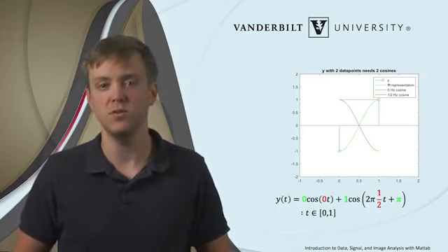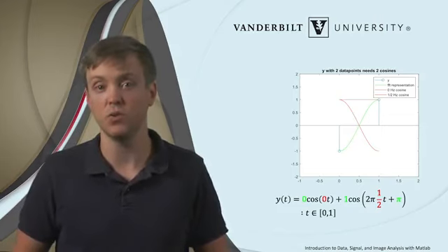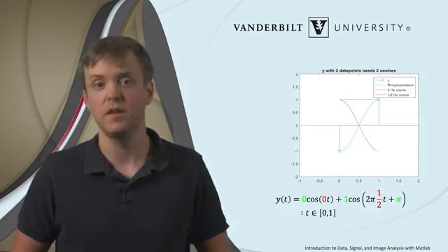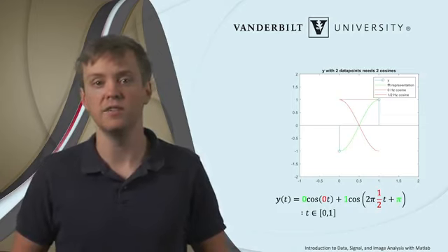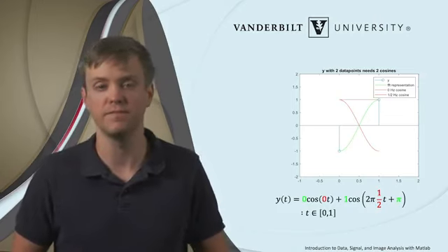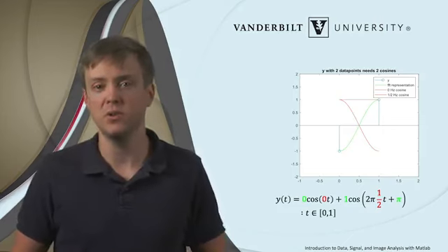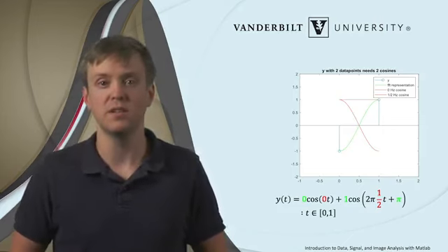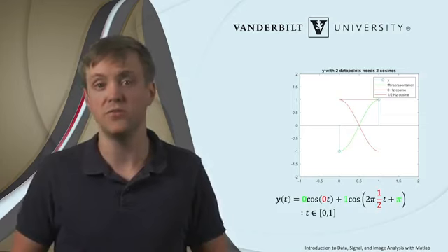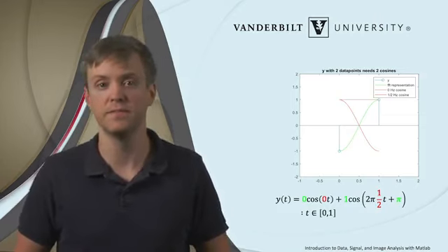A cosine with 0 frequency is just a constant. So we can see our 0 hertz cosine is a flat line equal to 1. A cosine with frequency fs over 2 and amplitude 1 with 0 phase looks like our 1/2 hertz cosine. The IFFT tells us that we need 0 of cosine 1 plus 1 of cosine 2 phase shifted by pi in order to approximate this signal.